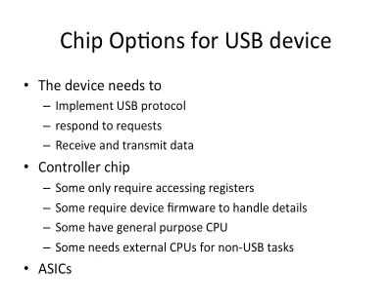The device, we said that we need to implement the USB protocol. It needs to respond to the request coming from the host. It will need to receive and transmit data. For USB controller chips, some only require accessing registers. You can implement USB functions. Well, some require device firmware to handle details.